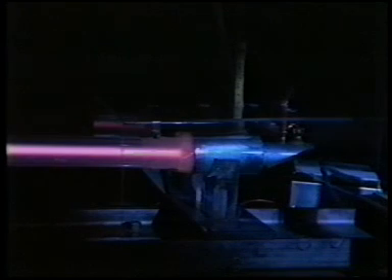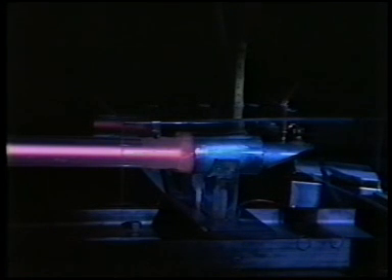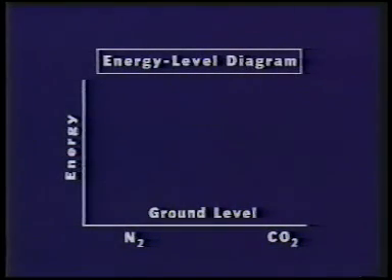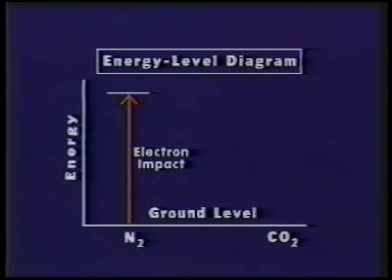For stimulated emission to occur, the carbon dioxide molecules must initially be put into an excited state. In order to excite the carbon dioxide molecule to the proper energy level, nitrogen gas is mixed with the CO2. The nitrogen is put into an excited state through collisions with high-energy electrons, which are generated from the electrical discharge. This energy is then efficiently transferred from the nitrogen molecules to the CO2 molecules upon collision between the two.